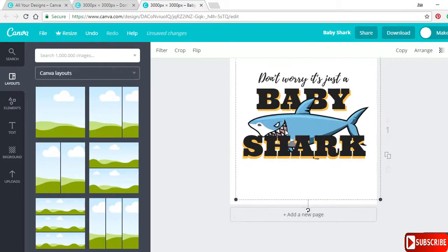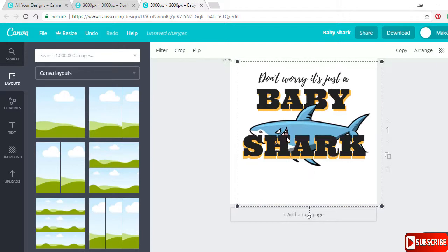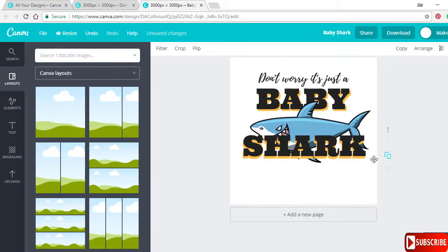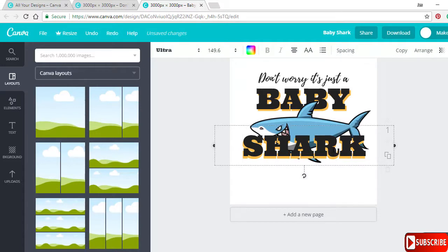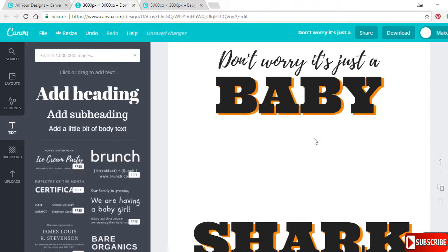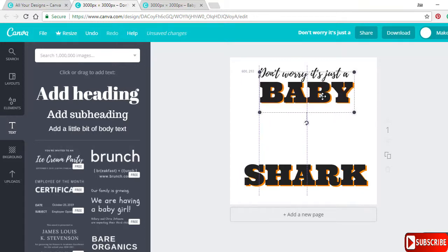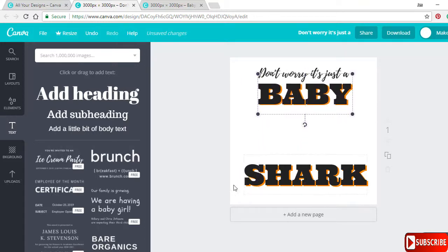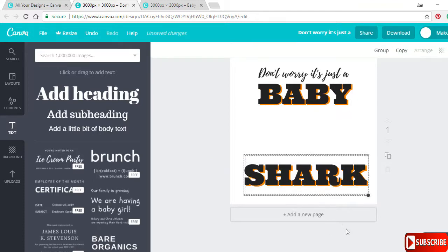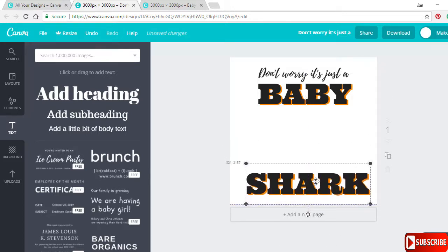Alright, now I can put it right here. Now that's the problem. You can group this actually. Now let's select this, just click and drag, make sure you select the word baby, group it, so when you move it, it's only one group now. Okay, the same thing with this one. Just make sure that you are happy with the spacing of the front and the back text, and then group it, so when you move it, it's only one object.